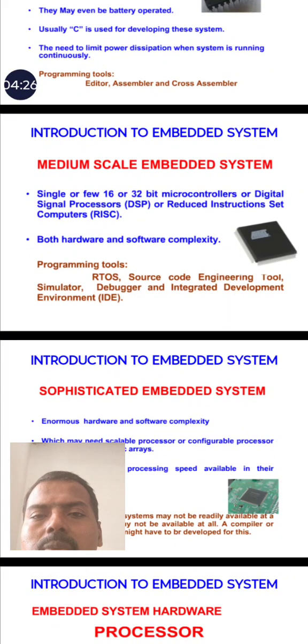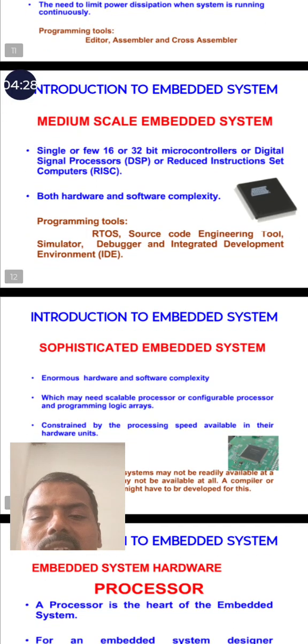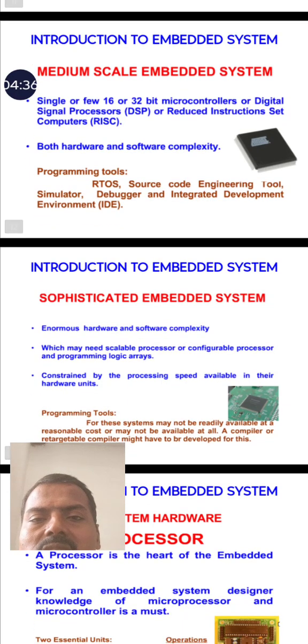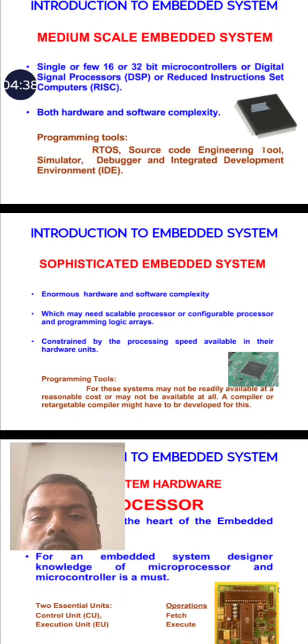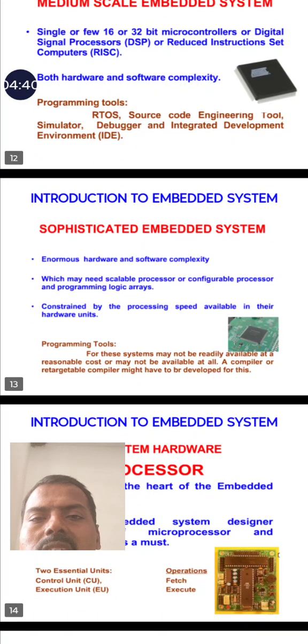Then the medium scale embedded system. It uses a 16 or 32-bit microcontroller, digital signal processor, or reduced instruction set computer, which is nothing but a RISC, with both hardware and software complexity. Programming tools are RTOS, source code engineering tools, simulator, and IDE, the integrated development environment.